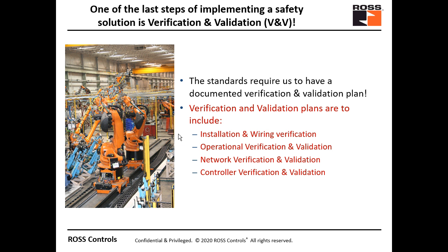And so one of the last steps when you are starting up and commissioning your safety system is you have to do validation and verification. A lot of people call it V&V. What has to be validated is I have to validate my wiring and make sure it has been wired right. So there's verification and validation of wiring. All right, did it operate as I intended it to operate? So you're looking at design verification and validation.